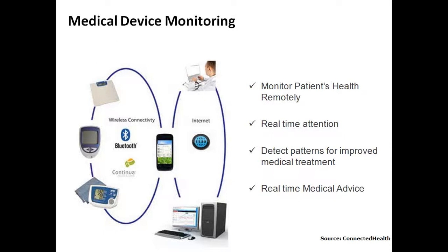What are some of the things that you might want to monitor are PV current and voltage measurements, how much energy you are generating, what are the fault conditions, if anything, efficiency of the solar panel. This obviously gives you a way to measure if your investment is performing to the level that you are expecting, if it is generating the amount of energy it is supposed to be generating. You could measure up to a specific string of solar panels to check if some of them are malfunctioning. All kinds of analysis are possible from the data that you could capture out of this. So from a simple standalone system, now from continuous real-time data collections, you have started to use the asset much more efficiently with the application of an end-to-end technology like this.